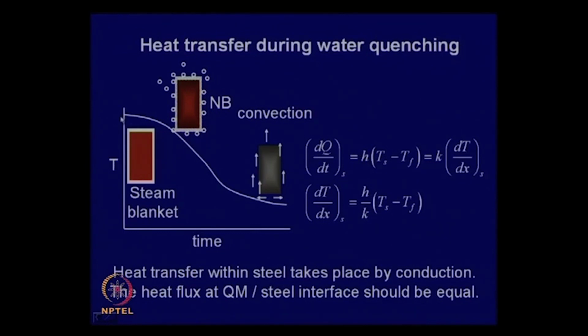And what you can see here is that the heat transfer coefficient changes with time depending on the actual mechanism, but the Grossman approach assumes a constant or effective heat transfer coefficient, so let us assume that it has an average or effective heat transfer coefficient. So, this is the rate at which you can extract heat from the job by convection from the surface.